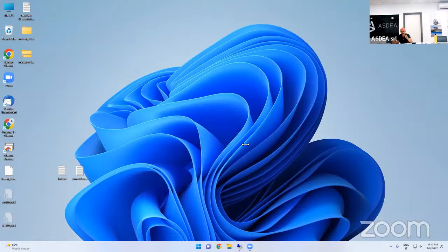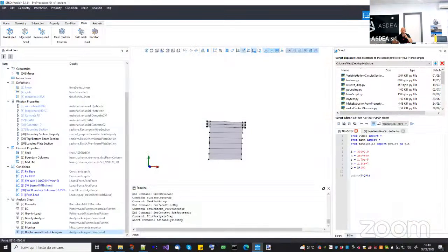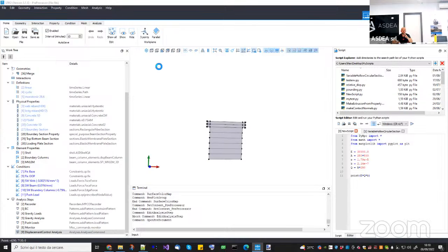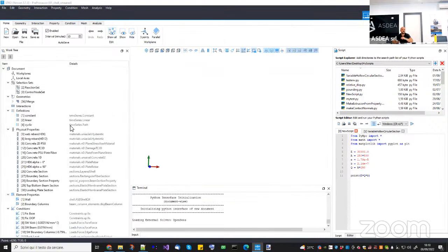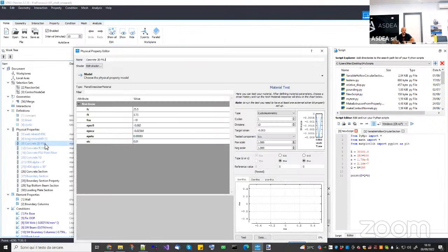And then you have two options. You can either use plane stress material, like the first one that you have seen. Let me go back to the first one, which was shell smear. In this case, I was using the plane stress user material. Now, this one is a plane stress material, which is pretty similar in the shape of the yield surface to the three-dimensional one. The point is that this one is plane stress, okay? It is still fine.